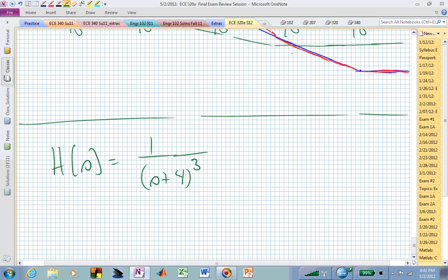So high would be 100 for sure. If we now look at the phase of this at omega equal to 100 radians per second, the j100 is dominating that 4, and now we really have 3 poles contributing 90 degrees. So now we have minus 90 3 times, so we should end up with this third order. And what does this look like in terms of a filter? If you had to say, what's the filtering shape of this curve, what would you claim that to be? Pardon? Take out a napkin, and what would your napkin tell you? It's a third order low pass, isn't it?